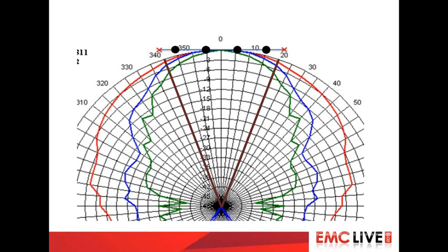Then if we look at the blue one, and do the same thing, go right, go right, go right, wait until it intersects with our brown line there, the limit of the zone of interest. I'm going to say that's 2 dB, given that's a 3 dB box. So at 1 gigahertz we've got a beam width loss of 1 dB. And at 9 gigahertz we've got one of maybe a little under 2, but I'm going to call it 2, because our system requires 10 gigahertz.